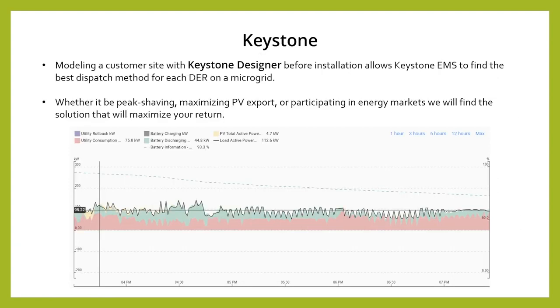Okay. You can continue to drill down, right? So this is something that your operational folks might care a great deal about is how granular can I get? And the answer is very granular. So we're going to go in increasing levels of detail here. This is sort of a more detailed screen that shows where is all the power going? Is it going to the utility? Is it going to charging or discharging batteries? What's the solar doing? What's the meter reading, right? There's a lot of different power flows to consider, and we try to consolidate that on one chart here so that you can kind of read it and look at it by color.